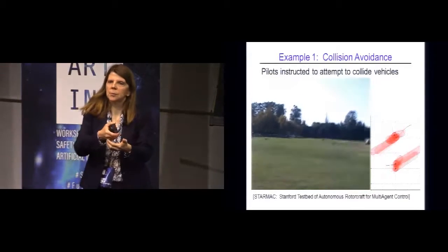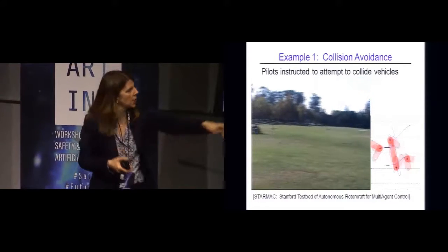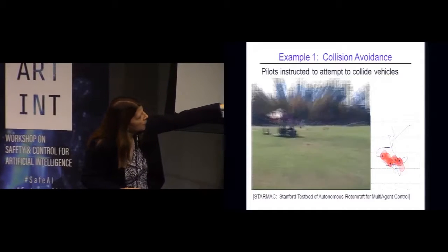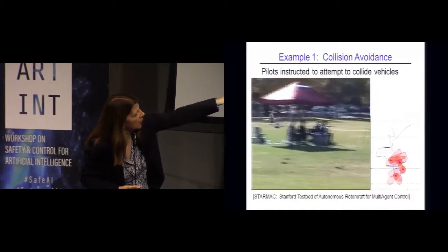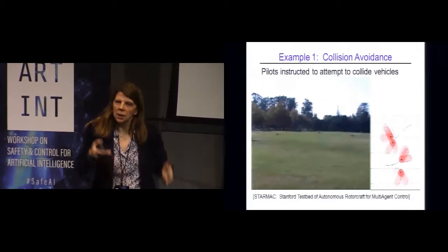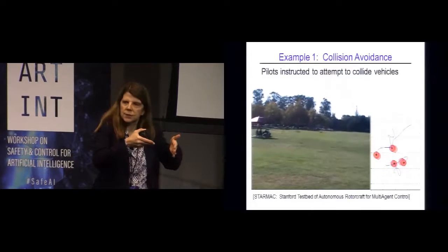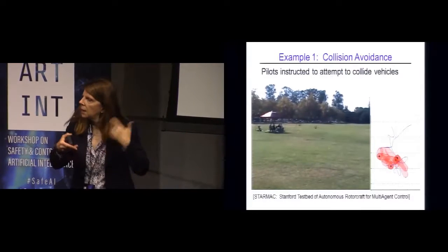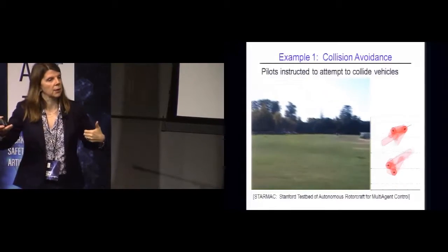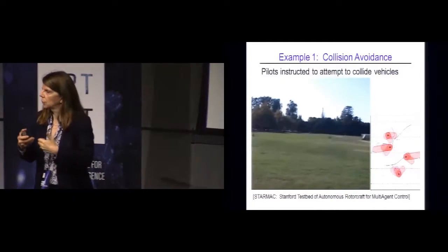And those are 4 graduate students. They're joysticking them around. And then when the aircraft come within the safety distance of each other, that's computed on board each aircraft, and I've displayed those safety regions. For each aircraft, there's 3 other aircraft, so you see 3 other relative safety zones around it. So if an aircraft touches the boundary of its unsafe zone with respect to one of the aircraft, then the experiment is that the autonomous control takes over and it guides the aircraft away from each other. So the pilots are trying to collide the aircraft, the autonomy takes over and won't let them collide.